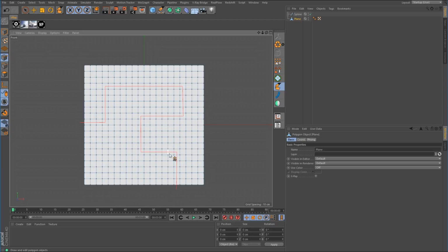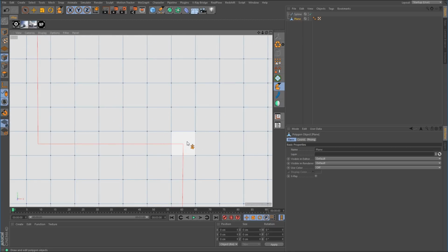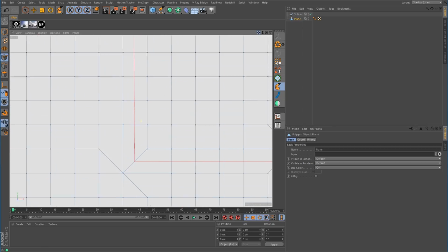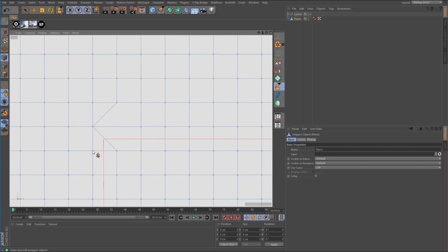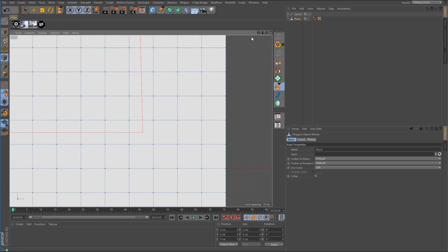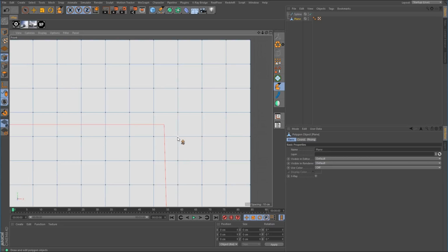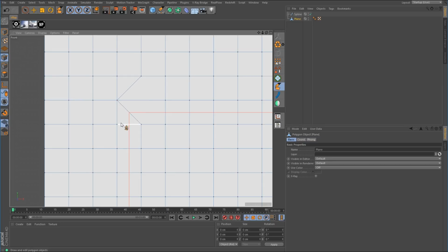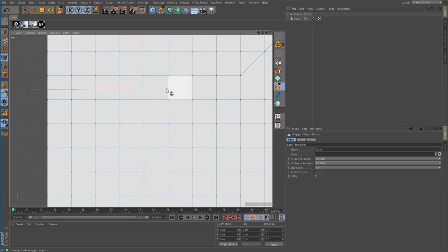All right, so I'm going to start down here at the bottom, at this polygon, and I'm just going to take these 3 points and weld them into one at that top corner. That's going to give us this diagonal cut, or this edge that's going to redirect our edge flow. We'll need to do the same here. We'll do the same here. And I think by now, most of you are getting the idea of what you need to do. So we'll do the same here. Do one here, and I think there's one more turn right here.